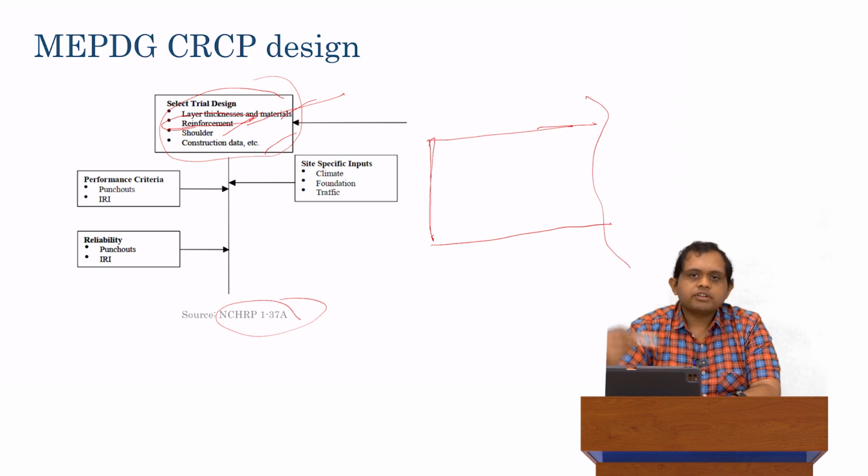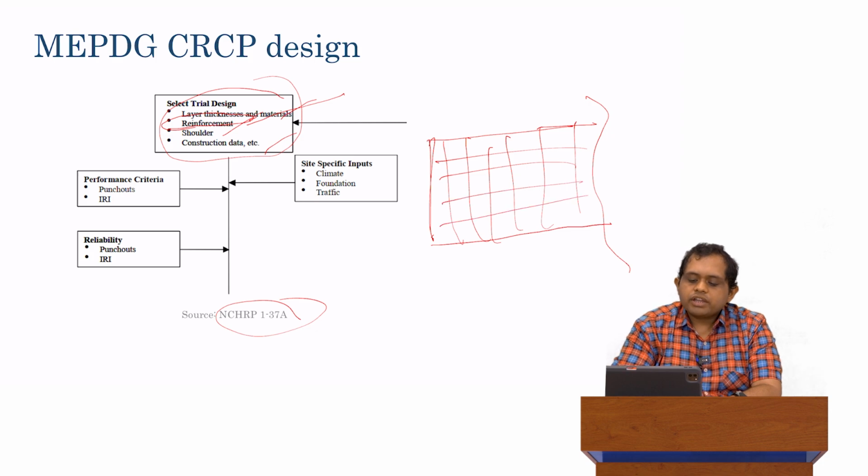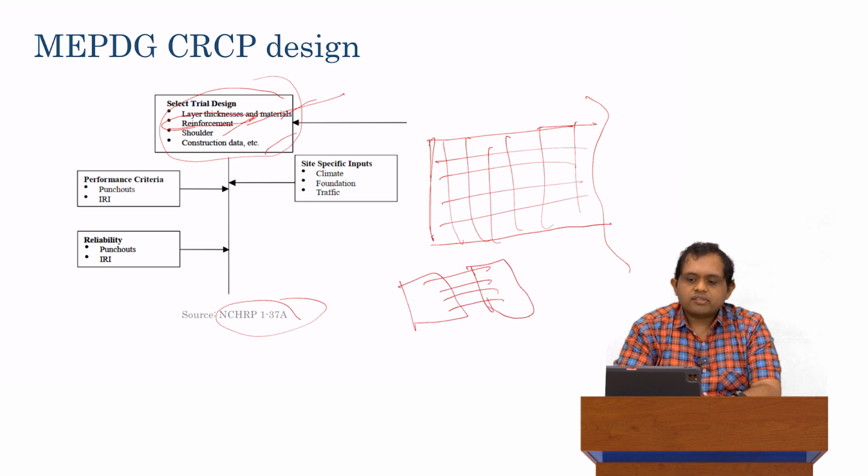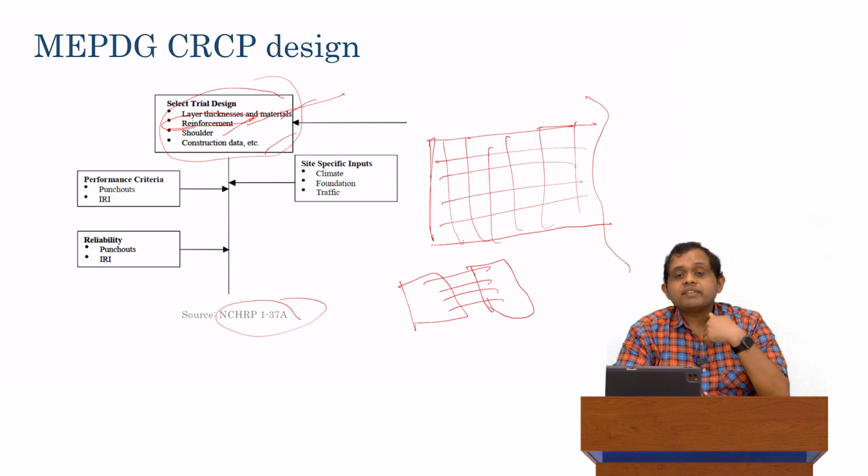So this basically goes on for the entire length of the road. But inside the pavement, we have a mesh of steel. So in JPCP, the steel is only present at the joints. In CRCP, the steel is present everywhere.